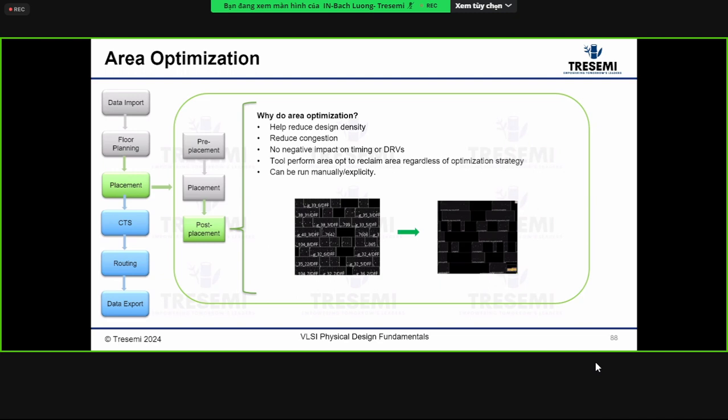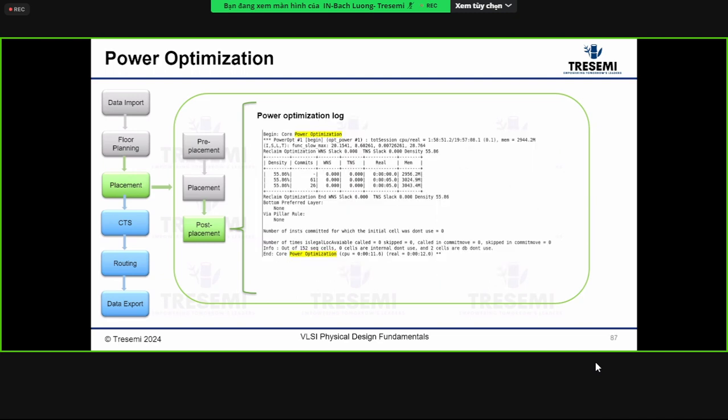Okay, so that was power. Any questions on power dissipation? Remember, we had 3 different types of power. You have switching power, internal power, which is a short circuit power, and then you have the leakage power. So at the low geometry, the leakage power is one of the most challenging to manage for designers. At a higher node, not so much, because the leakage power is only a portion of the total power.